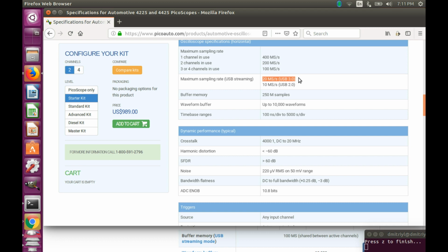That often means that you need to make sure that the USB port is dedicated to the Picoscope, and you cannot have anything else that will slow it down. So no USB hubs, and try not to connect other devices that use the USB port extensively.